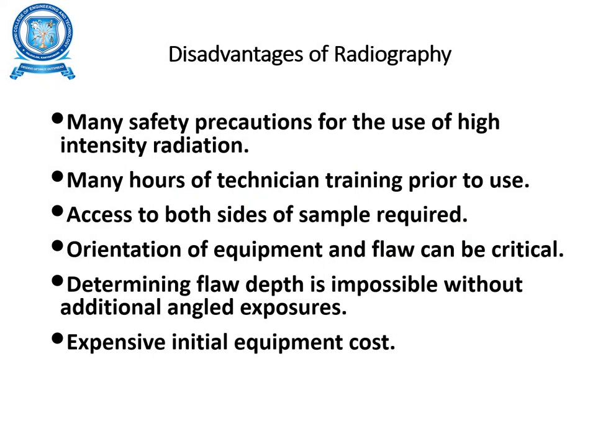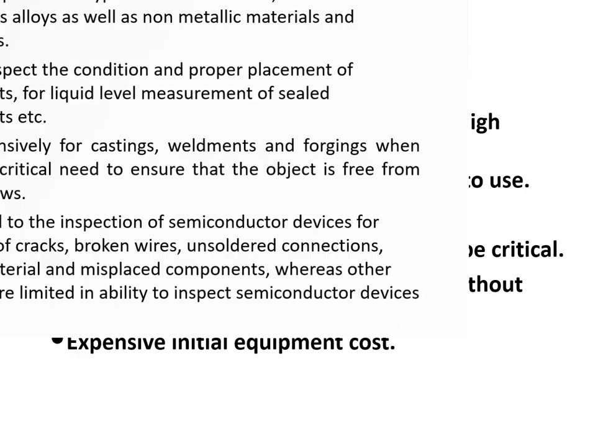You need to access both sides of the sample. Orientation of equipment and flaws can be very critical, flaw depth is impossible to determine without additional angle exposures, and there is an expensive initial equipment cost.